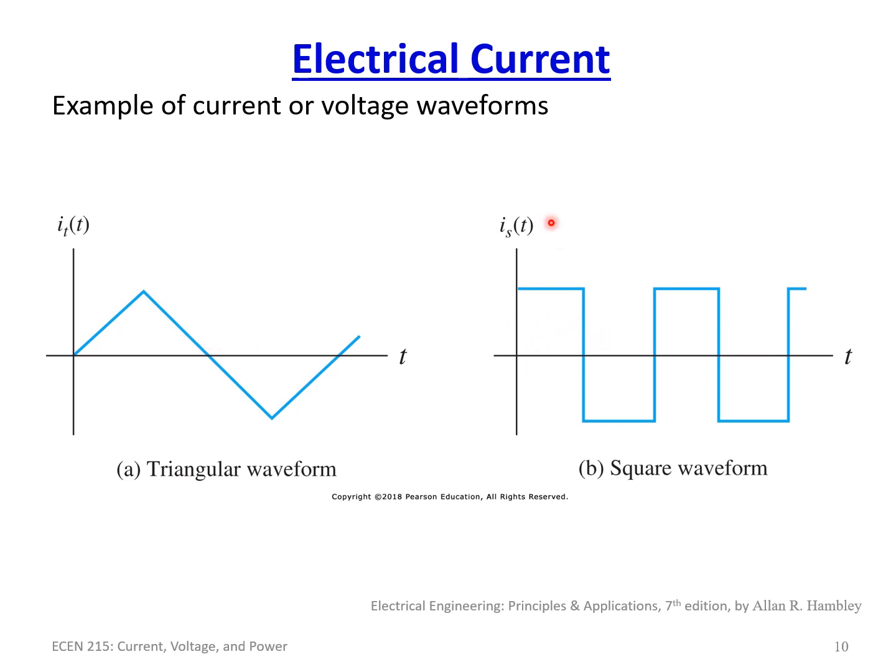And of course, a square waveform is kind of like DC in that it has a very fixed value, and then it automatically changes and goes negative. So this could be 2 amps and then minus 2 amps and then 2 amps and then minus 2 amps, and it's doing that at a period, at a rate specified. So for instance, 1 time a second would be half a second at 2 amps, and then half a second at minus 2 amps. And we'll be going over frequency and period later in the class, so you don't need to worry about what that means.